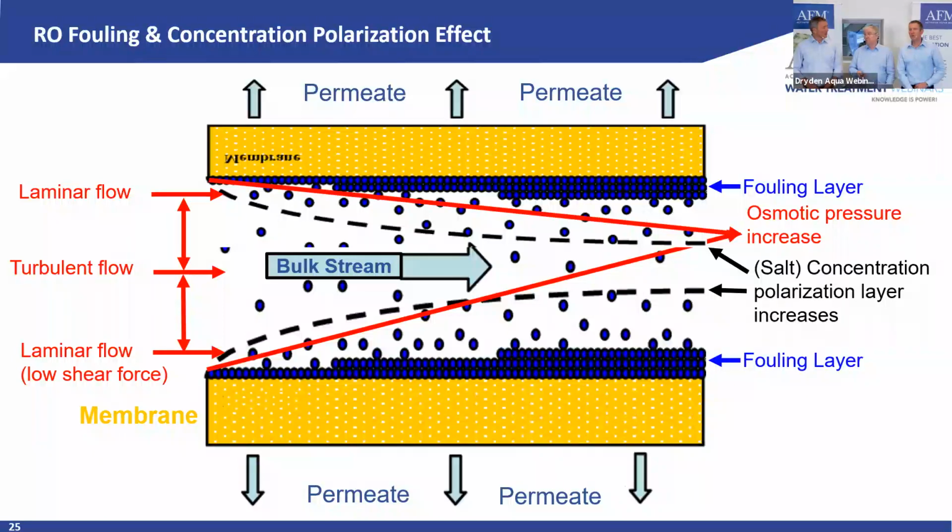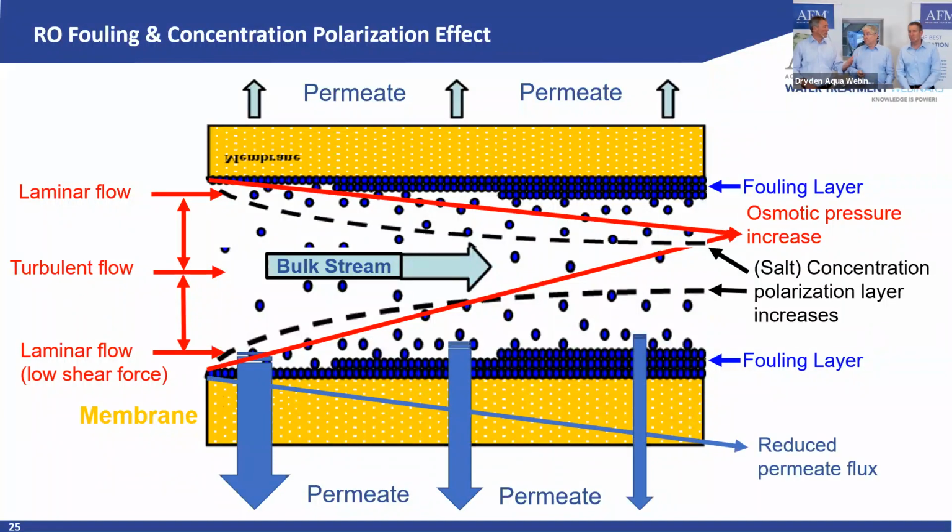And is this significant? Let's say we are in seawater desalination. Yes, seawater desalination is the biggest significant issue you can have. You run these plants at around 60 to 70 bars. Let's take 70 bars. And then when your osmotic pressure goes up, you have to increase this by, actually, 2 bars, 3 bars. This can go up dramatically because the salt concentration is up-concentrating here, and that's a really energy-intense problem.